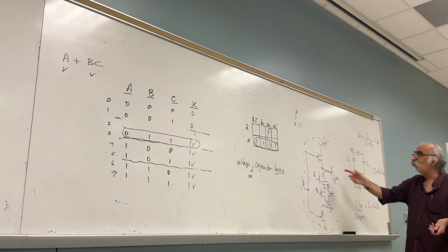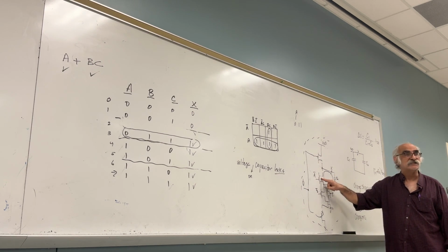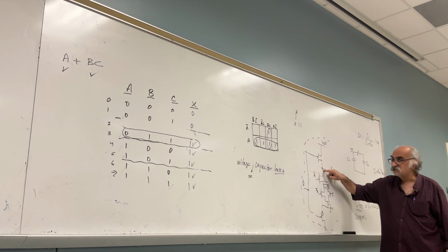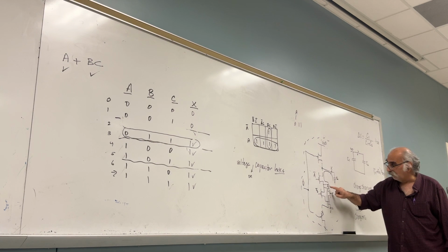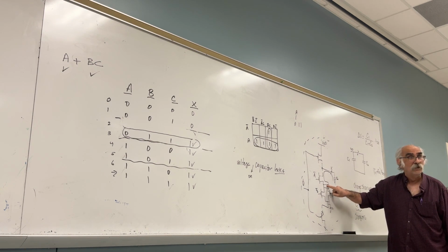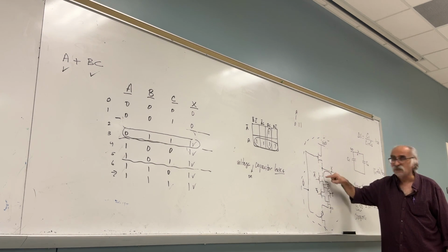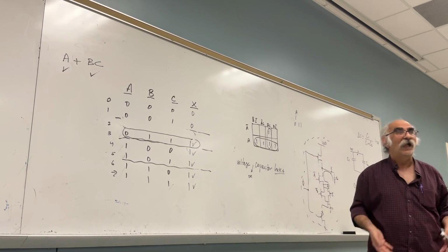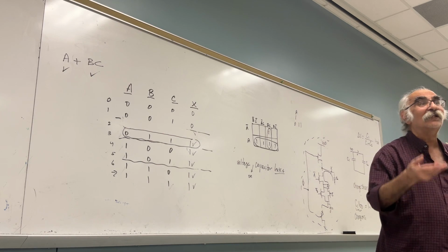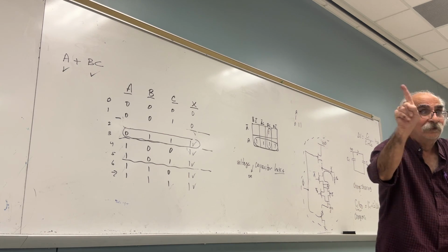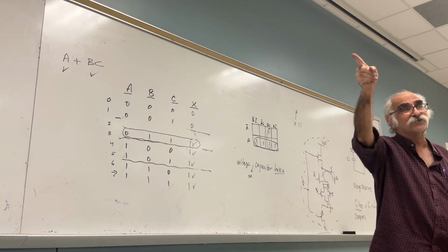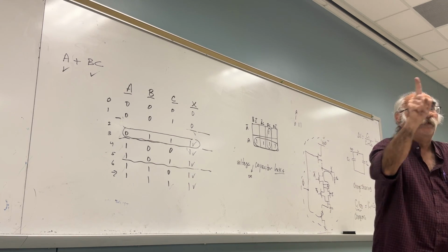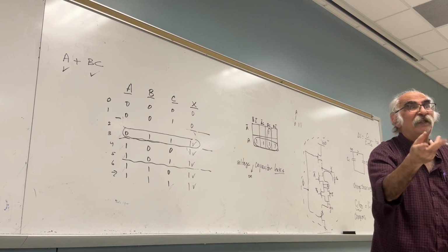I got your point. You are telling me the NMOS passes a weak one. So if this one is 1, this one is not going to be 1, because the NMOS passes a weak 1. Agree? I agree. What I'm saying is that there will be different voltages across C1 and C2. But eventually, they will be the same voltage.